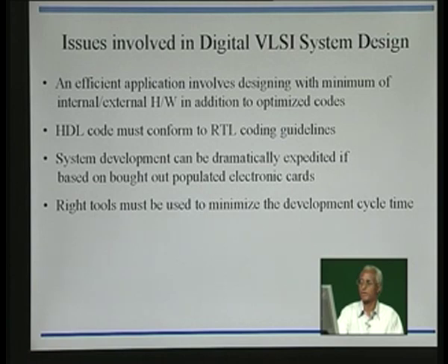You had to not only optimize your Verilog code, but also reduce the hardware to a minimum, both internal, in the sense of what is inside the FPGA that you have coded, and FPGA here also means ASIC. So, the design chip area is what I mean by internal here. External means you need to connect interface signals. No system will work without the interface. In fact, if you look at the cost considerations, it is the external hardware which takes more of the cost rather than the internal hardware, and this is true for most applications.